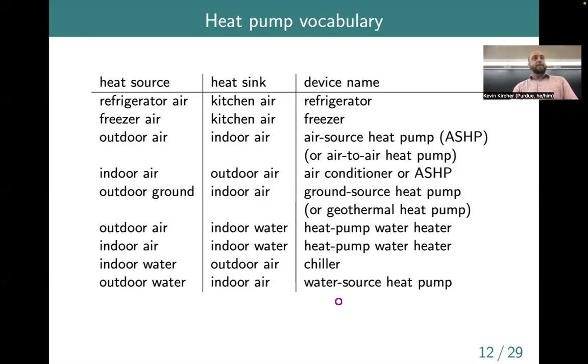Does the heat pump water heater also act as an air conditioner because it sucks heat from the indoor air? Yeah, so the question is, if you were doing this line, sucking heat out of the indoor air and moving it into water inside, is this thing also called an air conditioner? Typically you wouldn't point to the piece of equipment in the house and say this is an air conditioner, but yes, it does provide air conditioning. By that we mean cooling, so reducing the temperature of the air surrounding it, but also potentially dehumidification.